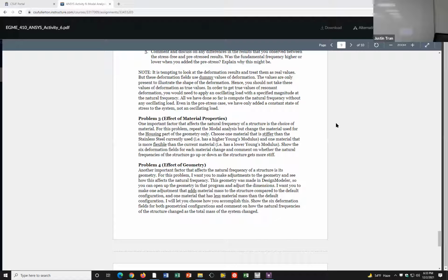You showed me what they say in properties appropriately. Yeah. So you go from Workbench, you're going to go to File, and then Save As, Archive. If you save as, it's going to save multiple files, but for archive, it's going to save like a single zip. And then once you open it up later, you just unzip the file. Basically.